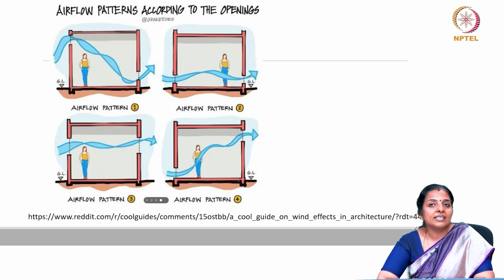If the air is incident on any of the other walls, then the door could act as the inlet to the room. Hence, again, the outlet would be larger than the inlet and the configuration would allow good air distribution.